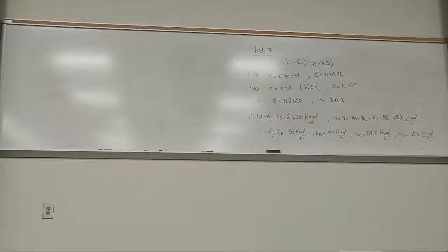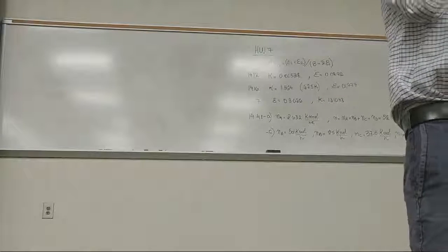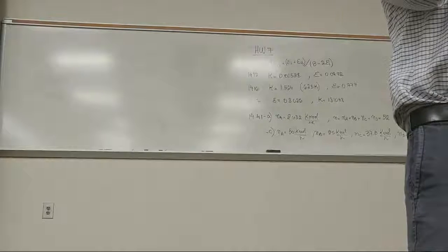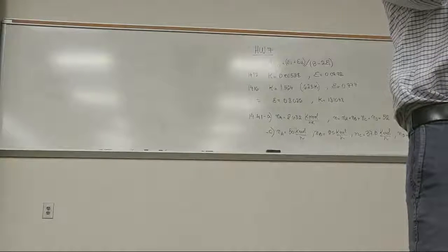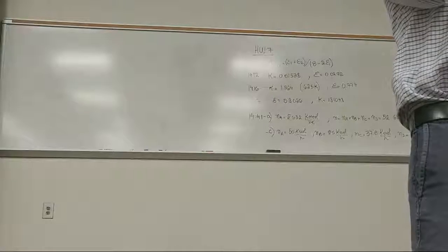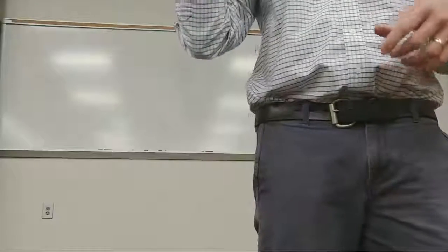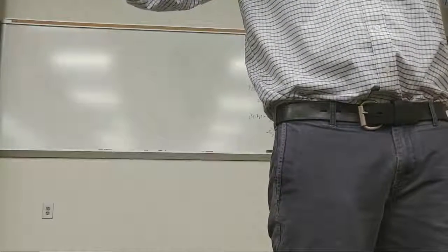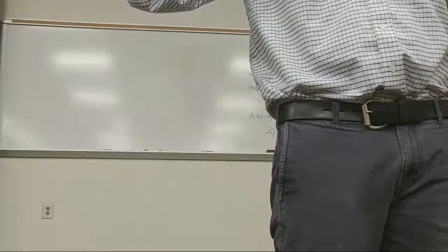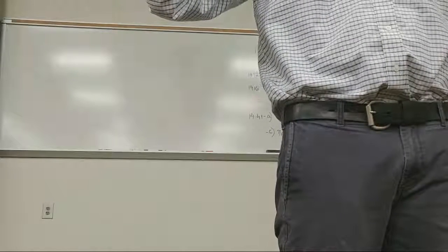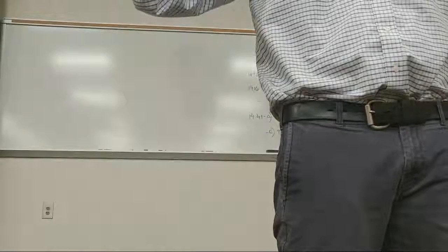One thing I failed to mention, and I need to do this here. Now, a Doppler shift always measures the shift in frequency due to the velocity of a projectile coming at the radar, from monostatic radars. It means if the radar is here, if a target's moving this way, then there's an apparent Doppler shift and it's measurable. And if it's coming at the actual radar, then the shift will be up in apparent frequency.